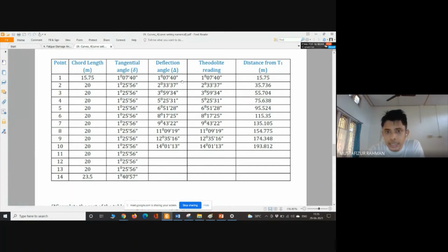Okay, so this is 40 seconds. Whenever it is a 20-second least count, we can give 20 second, we can give 40 second, then we can give 60 second or 1 minute. Next minute it will go, right? That way only the angles can be given in the theodolite. So this 40 seconds can be given, so it will be as it is.